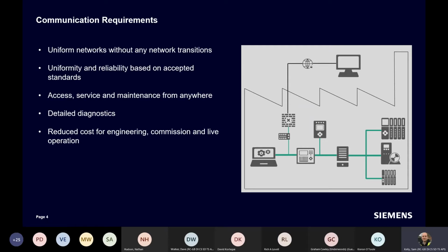from anywhere. Also, one of the benefits of Profinet, or one of the communications requirements, is that we want to have detailed diagnostics. We'll go through this later on in the upcoming slides, how Profinet gives rise to really good diagnostics information, and it's baked into the firmware of each individual device, and I'll prove that later on with a bit of a Wireshark capture.